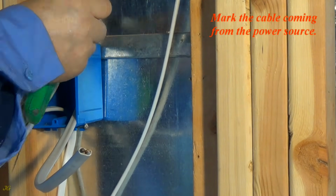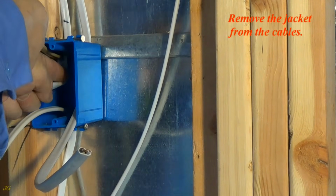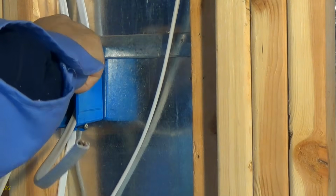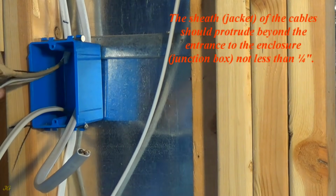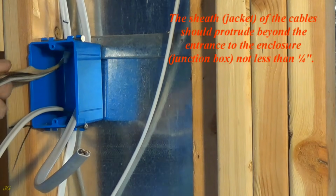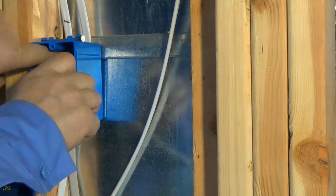Mark the cable coming from the power source. Remove the jacket from the cables. The sheath, jacket, of the cables should protrude beyond the entrance to the enclosure, junction box, not less than 1/4 inch.